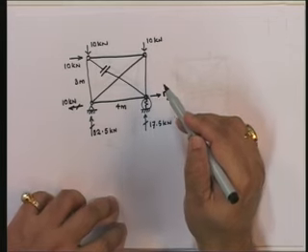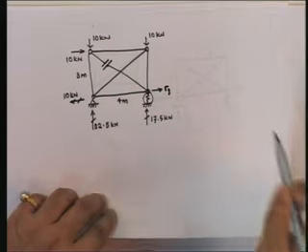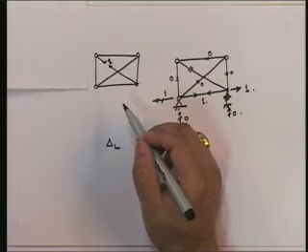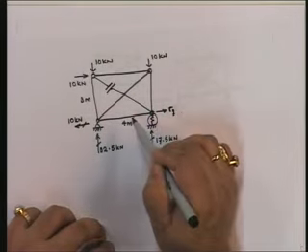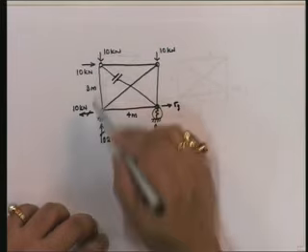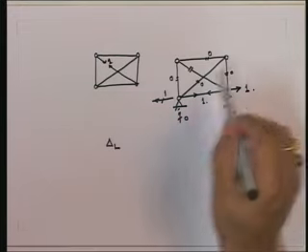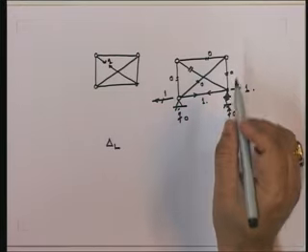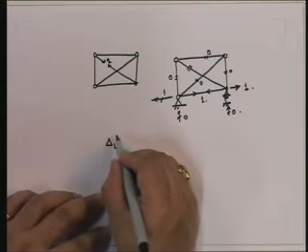We've already gone through the steps last time, so I'm not going to go back and do the same thing. You can find out this deflection and this deflection in this structure by just writing down the virtual work equations, where the real deformations at this point are multiplied by the virtual forces developed due to this and this. So understand that this delta L that I am finding out is what?